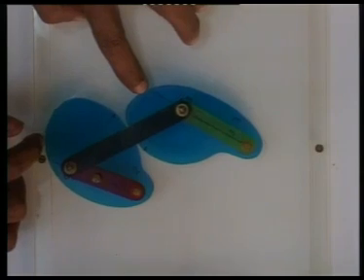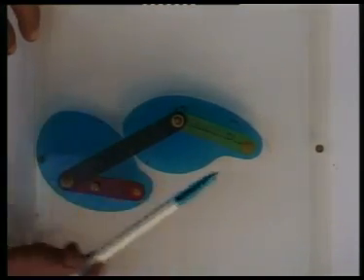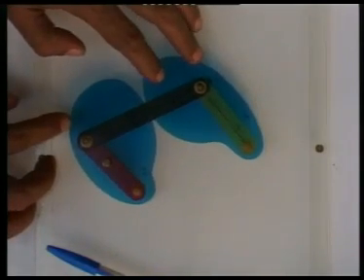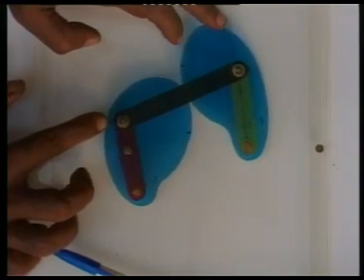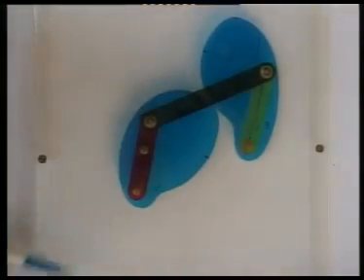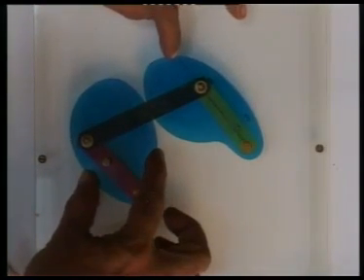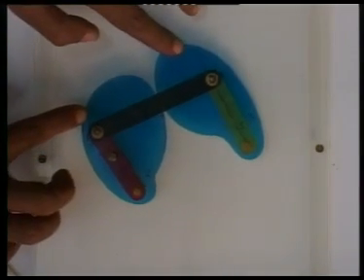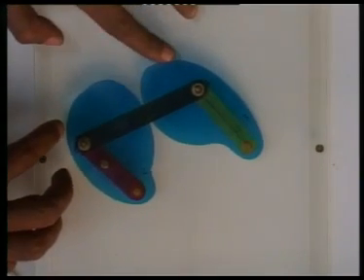But however, when there is a lot of movement, these two lines separate out. This blue line and this red line are not the same anymore. But around this point, it is only here that these two lines separate out, because the center of curvature is very different from what it was at this configuration. So this is what we mean by instantaneously equivalent lower pair linkage.